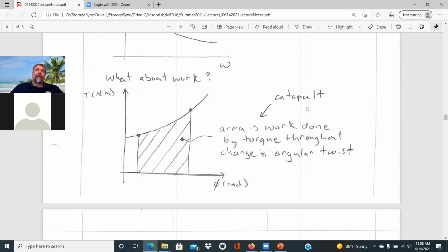And when you do that, you develop a lot of torque in the rope. You pin that in so it's not able to unwind, but then you kind of have a preload on the beam so that when you pull that back, you're causing that rope to twist even further and develop more torque. And then when you release it, that all gets released, say from that high point on the graph down to the low point, say where it hits the stop member, and launches the object.